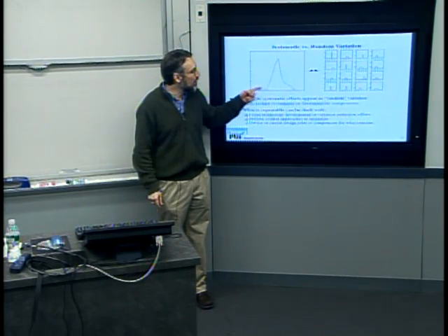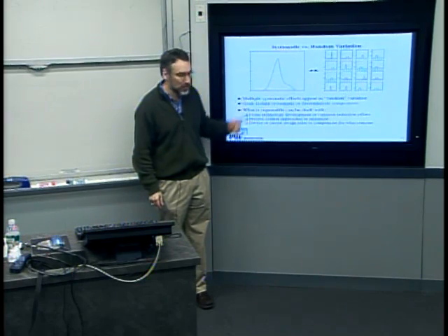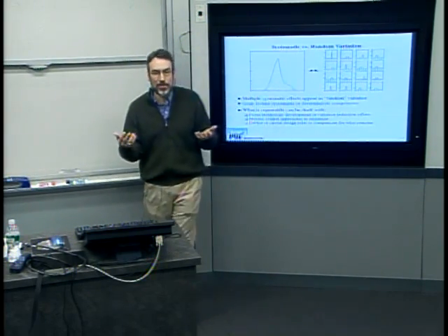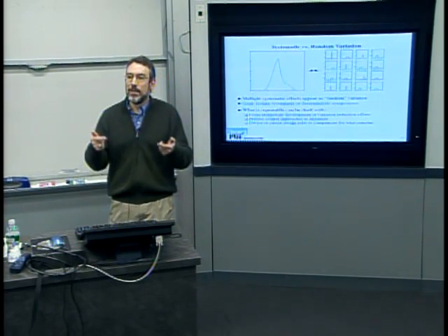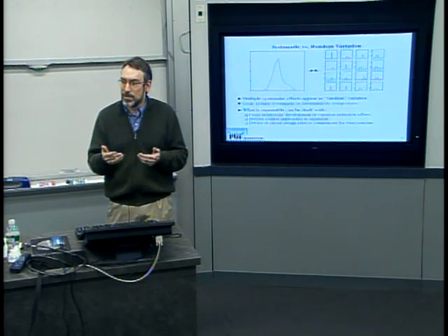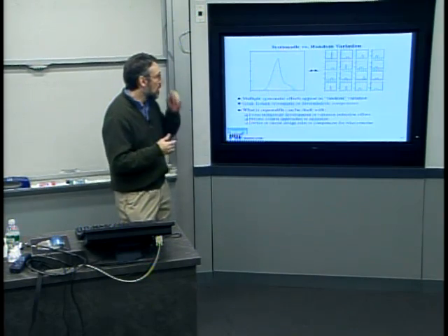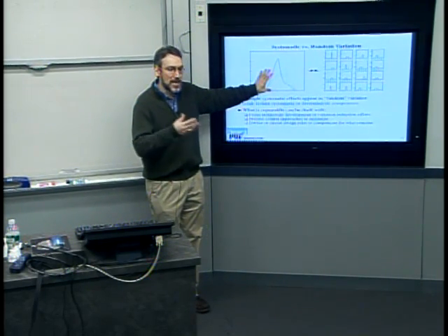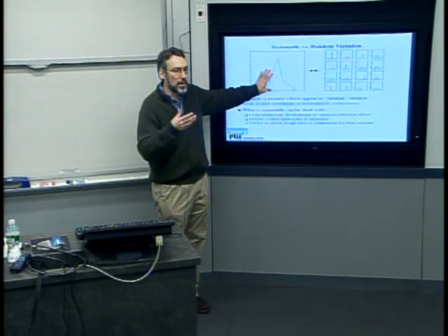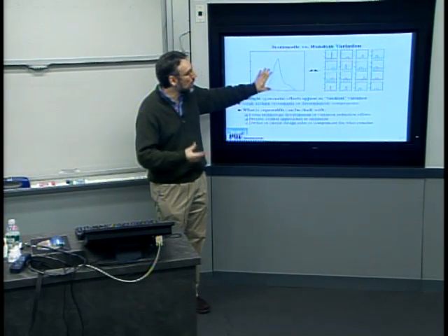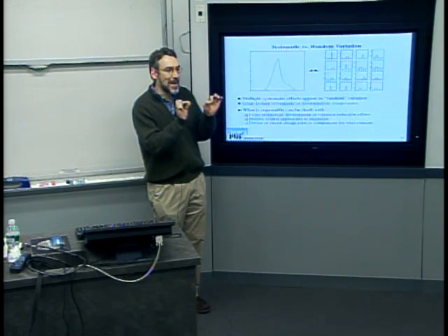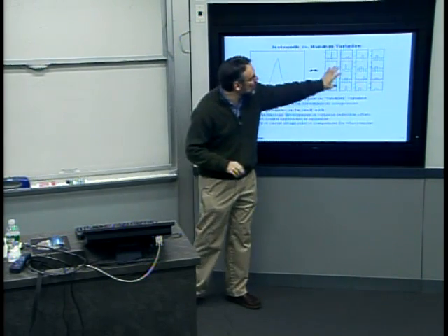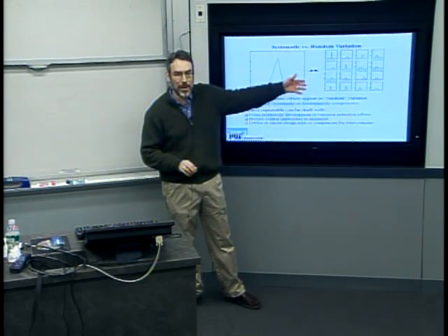And what's often very much the case and very interesting is that total distribution is the compounded effect of multiple additional sources that are sort of convolved together. And a lot of work will be done in designing test procedures, designing process control charts and whatnot to be able to track individual contributors and separate them out into the component sources of variation.